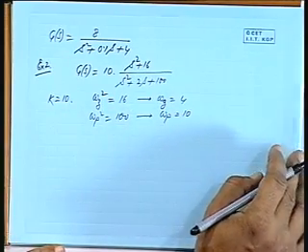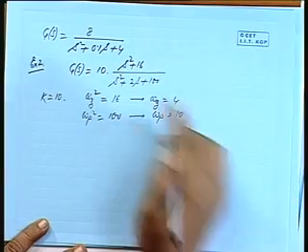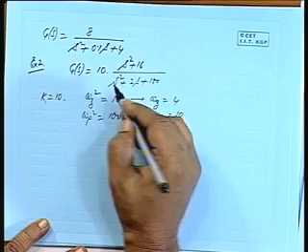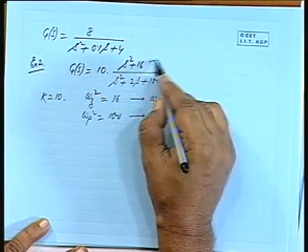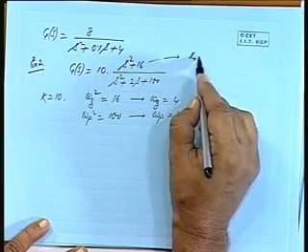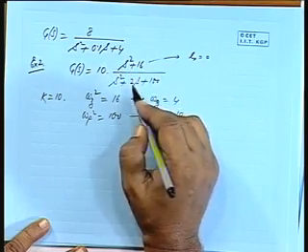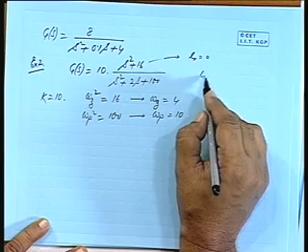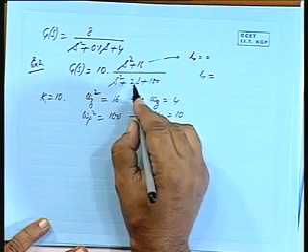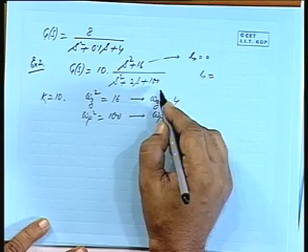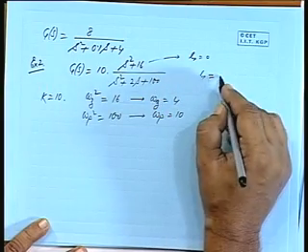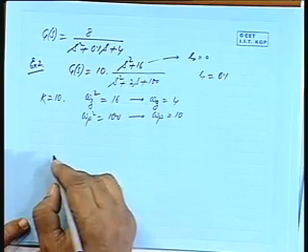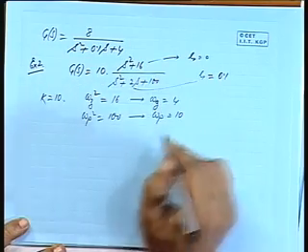Is that all right? And here, what is zeta for the numerator? Zeta in the numerator function is 0. There is no middle term. Zeta here you can calculate: 2 into zeta into 10 is 2. So zeta is 0.1. Okay. For the second one.